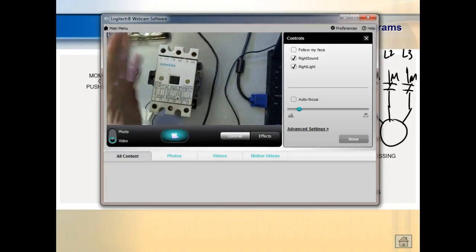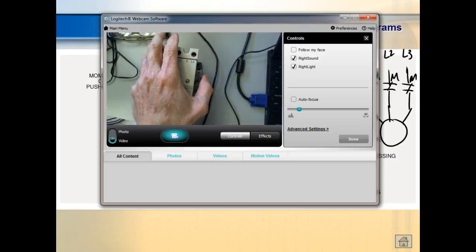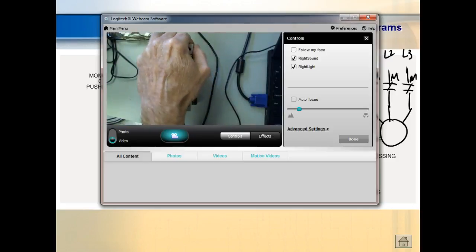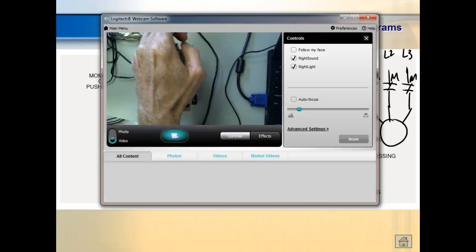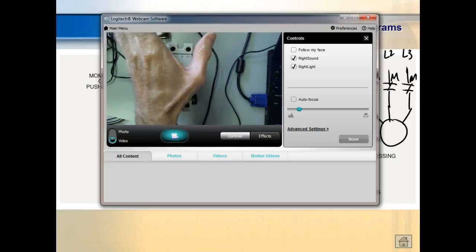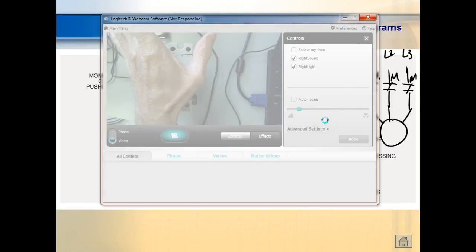So a contactor is a relay that's designed to run in both the control circuit and the power circuit, but it doesn't have overloads. So either the motor you're going to run has overloads built into it, or it's going to run some other power device that doesn't require overloads. You'll understand that. So what are the overloads in there for? Well, it allows us to fuse the circuit at the start current and still protect the motor, because your fuses have to let the start current get through, right? You understand that?